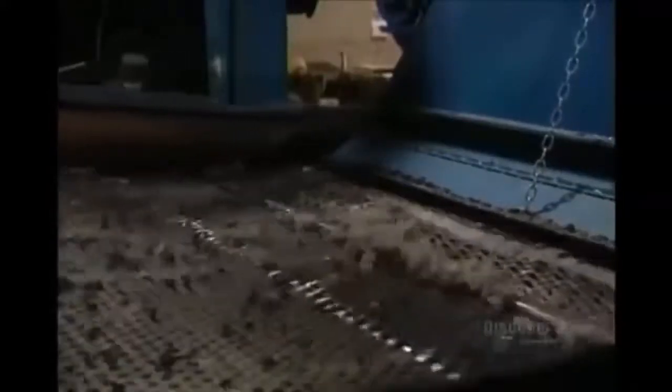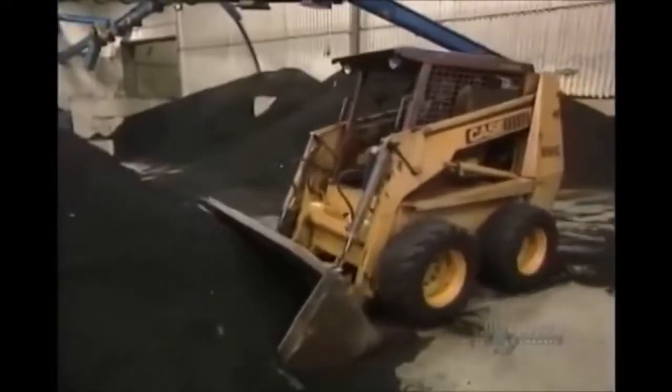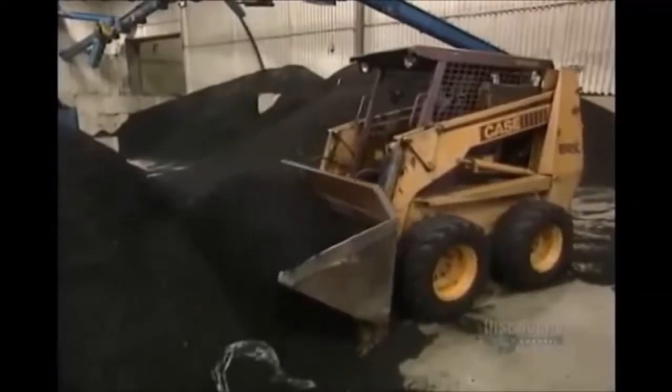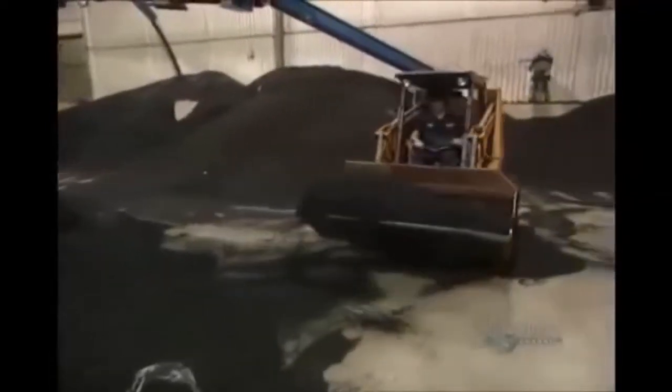Other components of the tires, such as fiberglass and nylon, also have to be separated. They use a sifter to get out unwanted rubbish. Recuperated rubber particles purged of foreign materials measure about 2.5 millimeters. Some 16 tons of tire particles are piled up in this recycling depot. But the particles are still too large to be used. They're sent to a secondary shredder's supply tank where they'll be reduced even further.